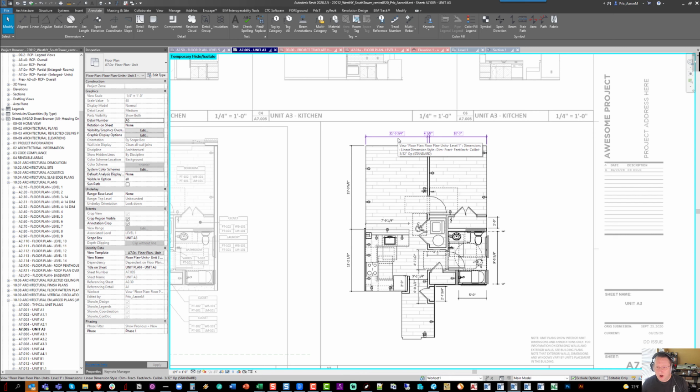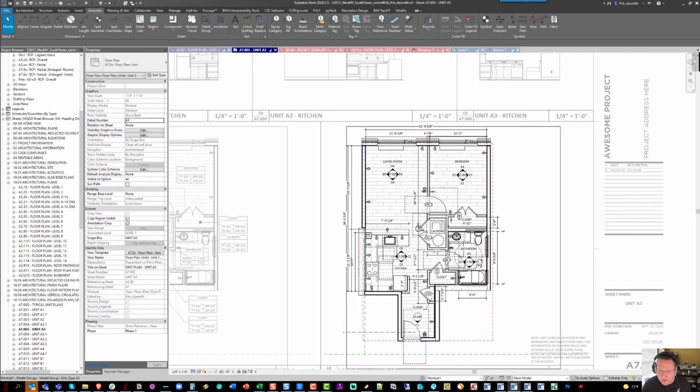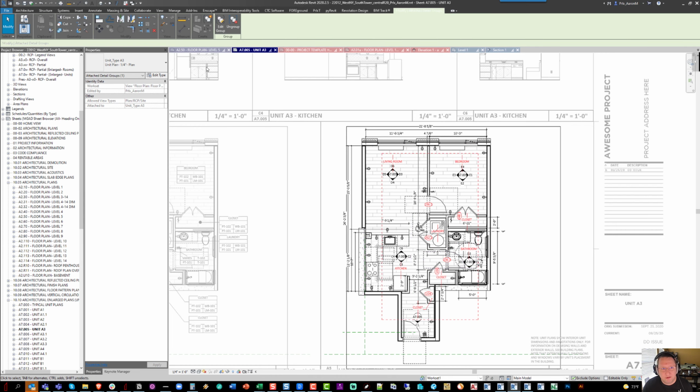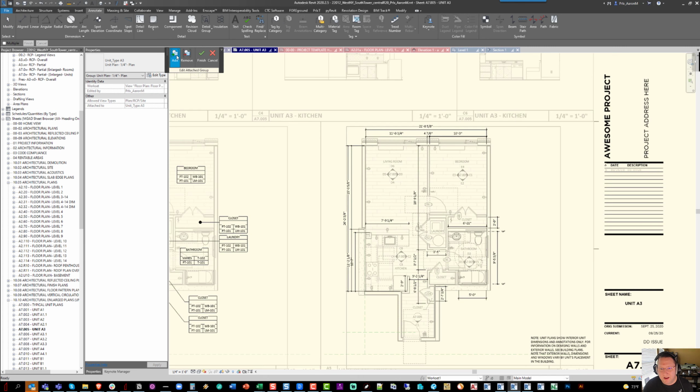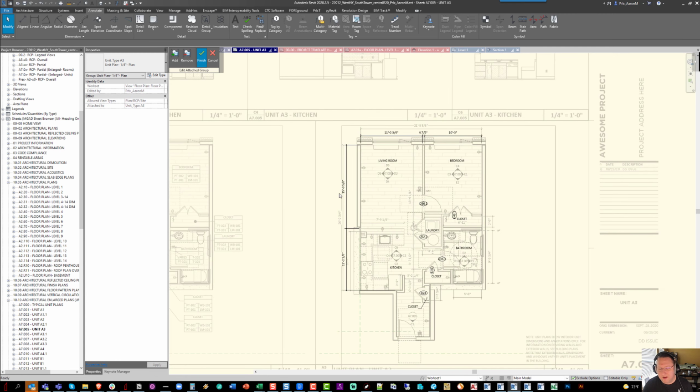This is the part of harvesting that's a little different from creating a brand new group, is when you harvest, you will have to replace some dimensions that are touching items outside the group. But now, if we were to take this group and select actually the detail group that's within it, and to do that, we'll have to actually reset because we hid them. So if you tab down, you will be able to grab the detail group itself and you can edit that directly. You don't have to go directly through from the model group. And then you can add in the new items that we put in, such as this dimension string here and this dimension string here. Now, obviously, I'm not going to do all the rest of the dimensions, but that'll basically accomplish the same goal.